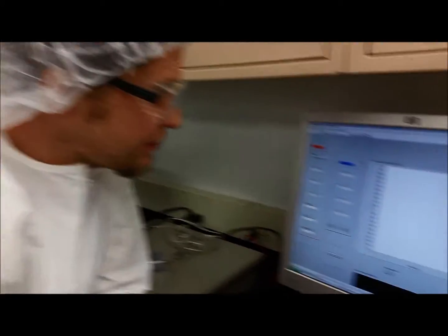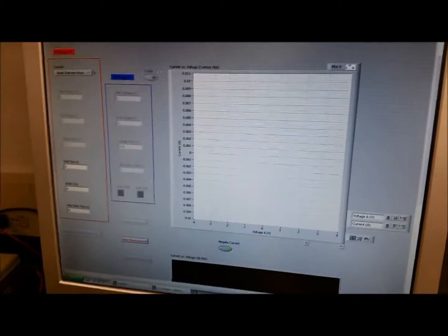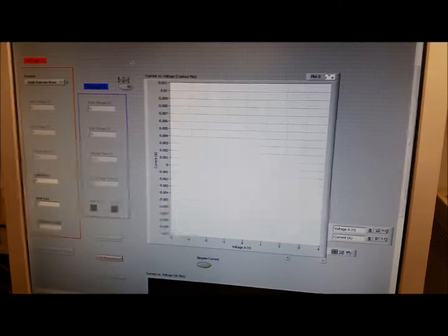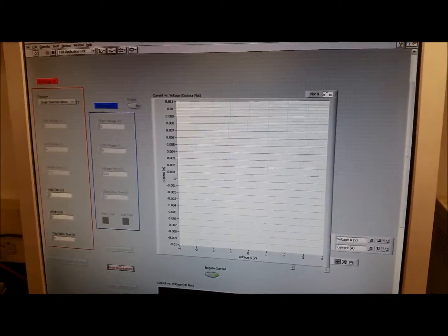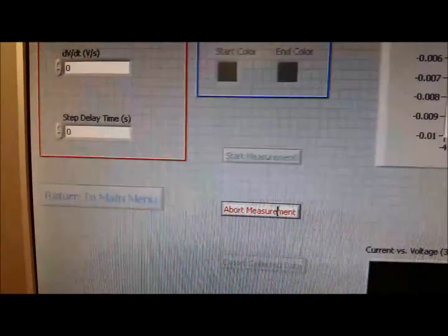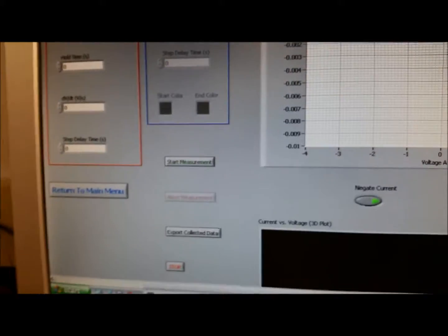When working with a LabVIEW virtual instrument, it's important to remember that the machine won't actually run until you've run the virtual instrument. The way that happens is you'll first diagnose it when you try to click on things, and things just kind of underline or perhaps even try to move buttons like this. That's really inconvenient for us. What we have to do is start the machine. So to do that, we go to the top left portion of the screen, and we see this button here that says Start. We click on Start, and now our virtual instrument is in the operating mode.